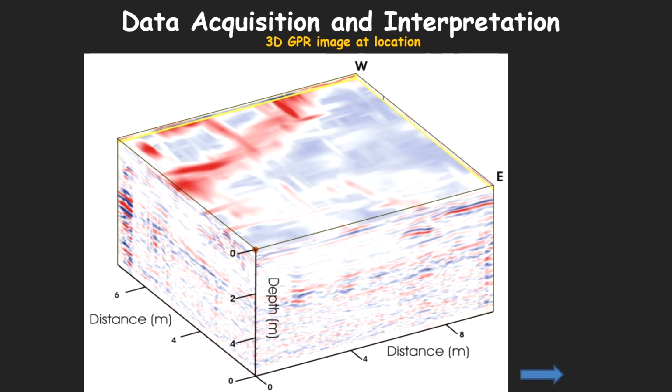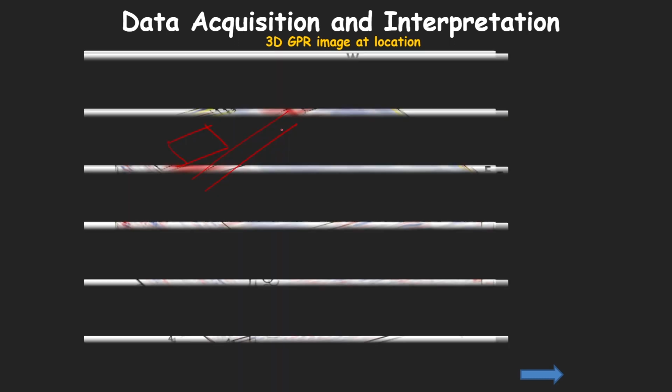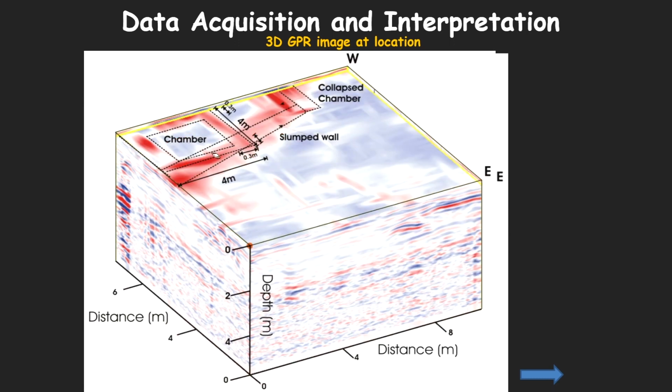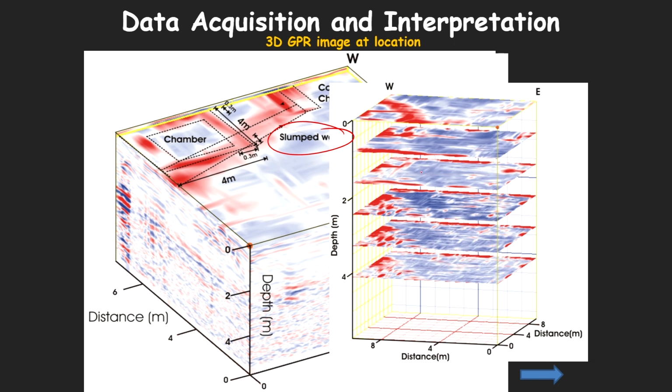Now, another part: we were also able to pick up the crisscross relationship of the structures, because one wall structure we could see here, but another one was here. The next interpretation, as you see, is what we have marked. Probably this was another wall along with this one, or maybe the brick beds we see here might have collapsed, and that is one of the reasons why we see this crisscross. Again, we saw at depth that it doesn't extend.